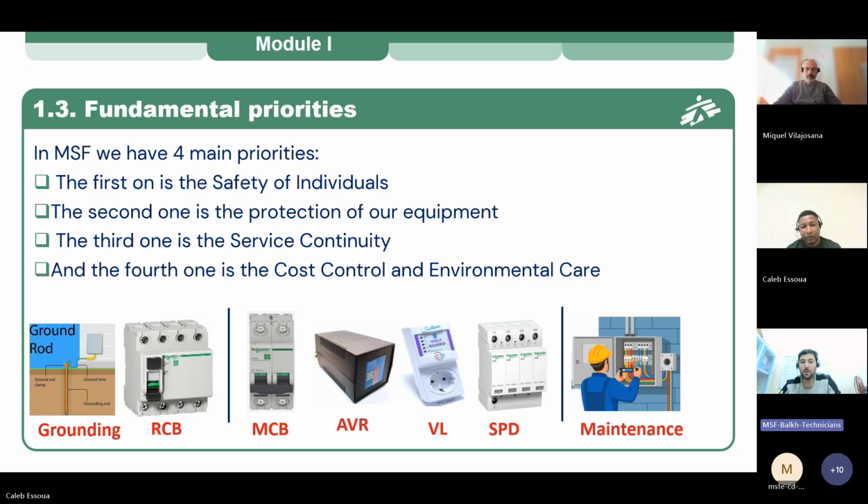So we should not install the voltage limiter when we have a voltage regulator? No, we can install it. What the voltage limiter is doing is just checking the range of the voltage that it's supposed to check. If it's out of range, it just disconnects, and then your device stays safe. So you can install your voltage limiter on your device.